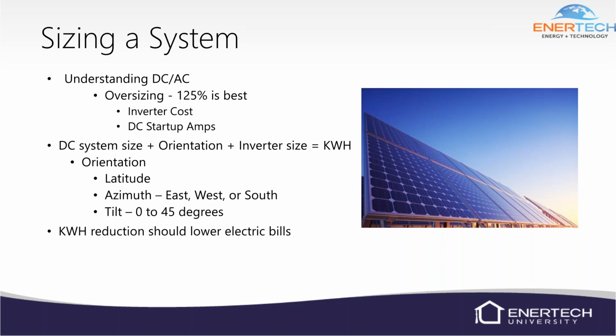When we say orientation, I think the rest is self-explanatory, but the orientation means the latitude of where you sit. You could be in Canada, you could be in Florida, but depending on where you are on the earth depends on how we orient the panels to the sun. And then the azimuth is the east, west, or south, and we talk about that as well. So the best performance likely is south facing, if at all possible.